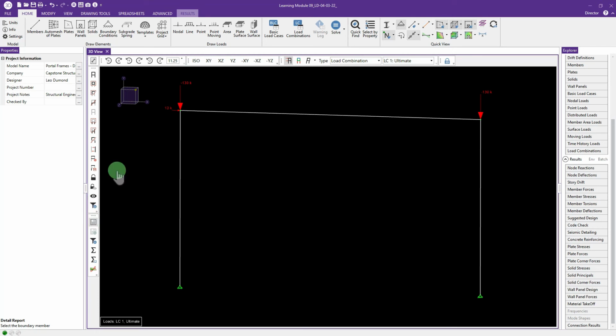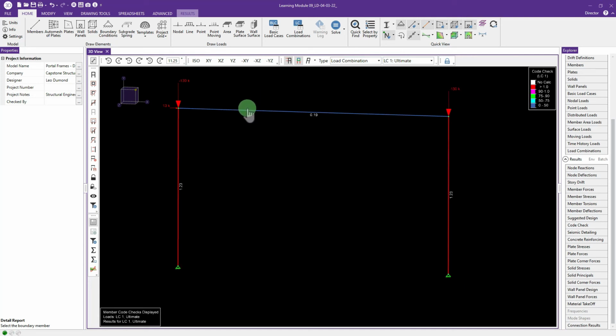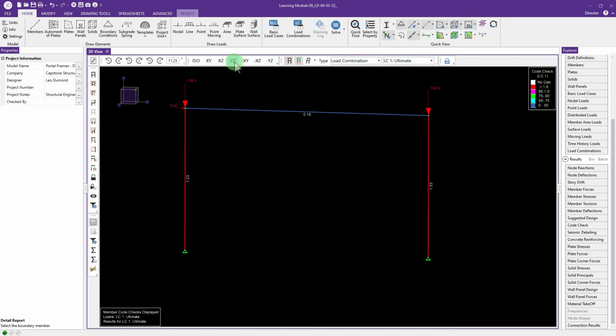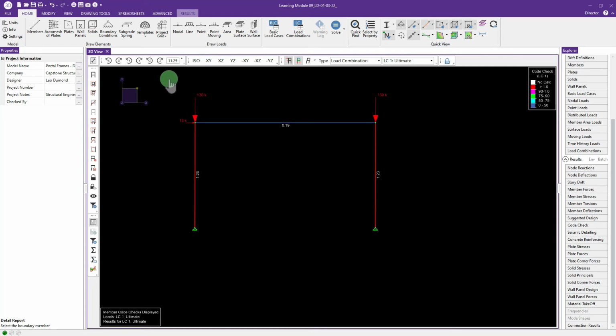All right, let's go ahead and take a look at our stress ratios here. You'll see it probably jumps up to closer to that 23% overstress value. There you go, right on the head. All right, save. Let's go ahead and show what does work. Actually, nope, let's do what we always do and increase our number of nodes here, our number of elements.